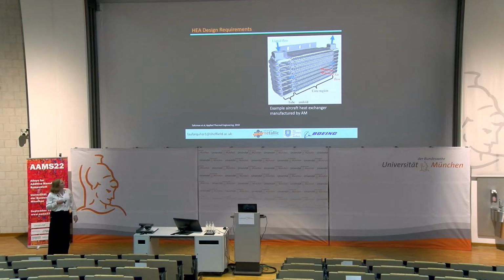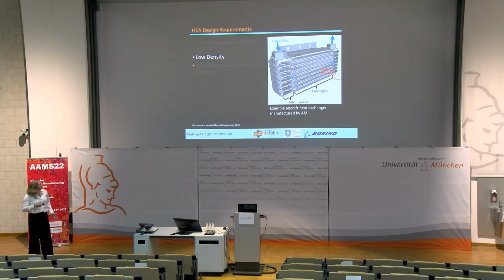And we need to be able to manufacture this by AM. So our operating temperature is at over 1200 degrees. We obviously want a low density alloy because it's for an aerospace engine. And crucially, we're looking for a single or multi-phase solid solution because, well, for 2 reasons. One, we're trying to mimic the possible multi-phase alloys that you see, like conventional superalloys, and we're looking for that weldability.